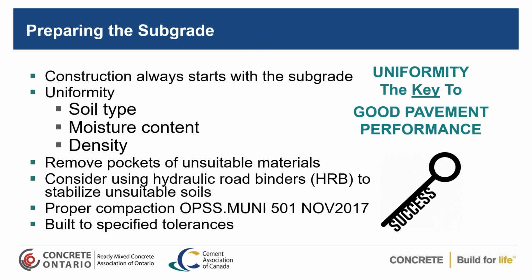So the key to performance is uniformity. You're going to have a geotechnical investigation. You're going to know the soil type, and you're going to know the moisture contents and the densities that you're going to be working with. And you want to remove any unsuitable soils.